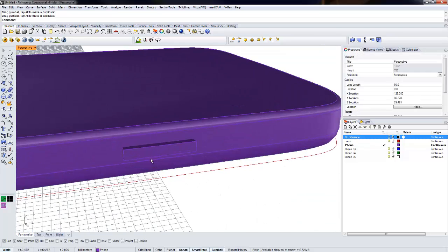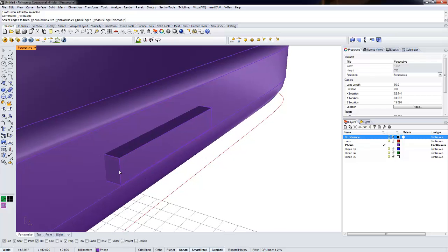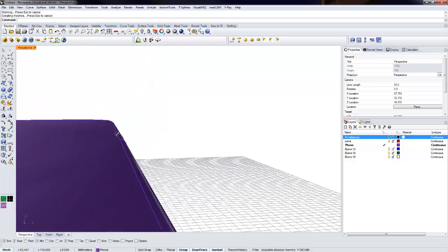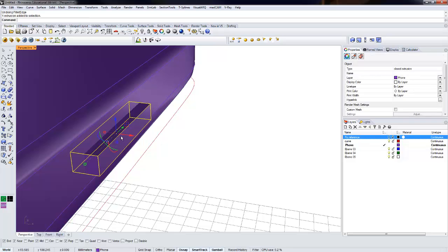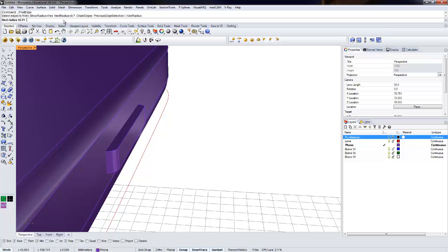Okay. And now we're gonna bevel the edges. So go on the solid fillet edge. First we're gonna take this one. Maybe 3 is too much. Change the radius to 1. Okay, that will work. Maybe put it a little bit more inside because it's not that much. Again, radius, maybe make it 0.7. A little bit less than before. Yeah, it looks better. And now we're gonna bevel the other edges with 0.3 or something. Just select all of them.